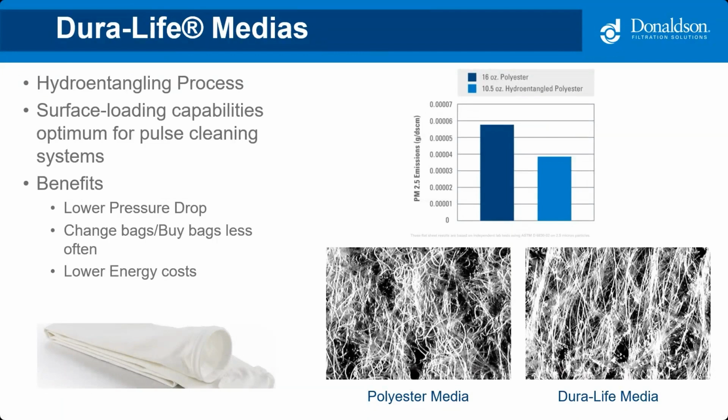But here are a couple red flag areas in the foundry industries. I'd be careful if it's in a real abrasive environment. If you have filter bags that are getting a lot of holes in them, Duralife might not be the answer because it is a lighter weight fabric. But if you don't have any abrasion issues, it can really help out with the capture of fine dust to help with your emissions.